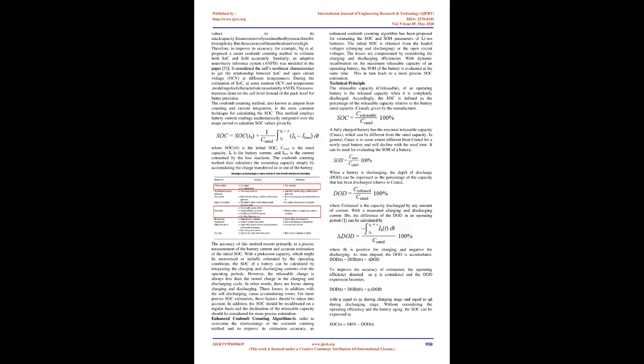Traditional approaches to state of charge estimation, such as open circuit voltage, OCV, measurement and current integration, Coulomb counting, can be reasonably accurate for cell chemistries with a significant OCV variation throughout the SOC range, as long as the current measurement is accurate. However, estimating the state of charge for battery chemistries that exhibit a flat OCV-SOC discharge signature, such as lithium iron phosphate, LFP, is challenging.